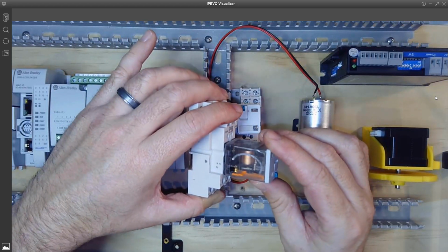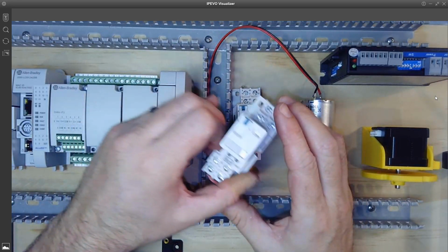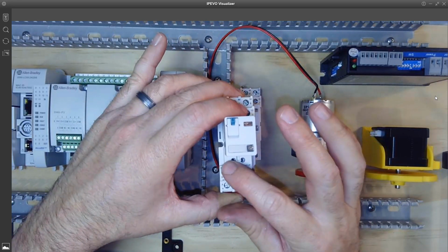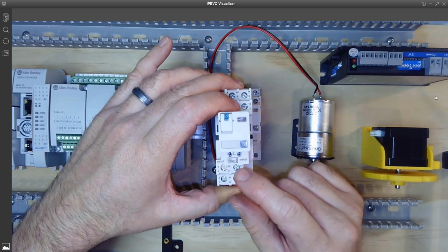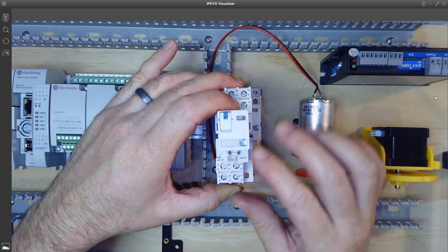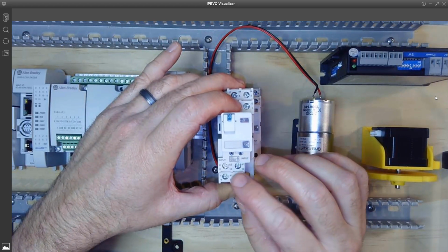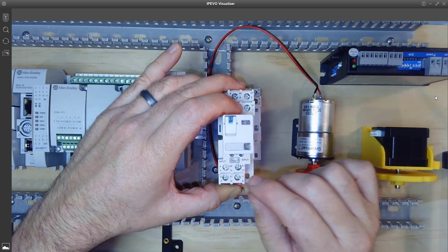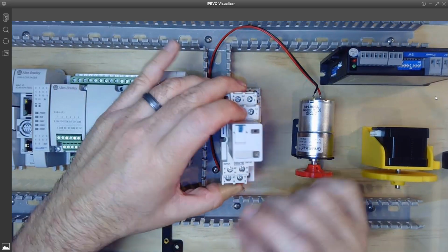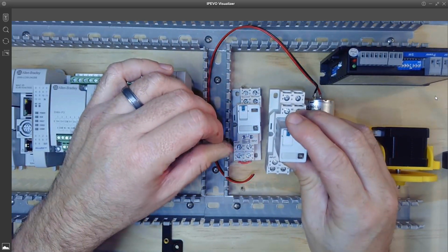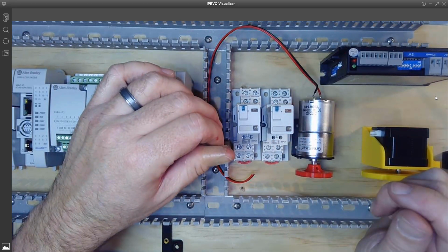And again, we talked about this briefly back in MEC233. The way we do that for a DC supply is we put a diode across the coil so that the diode blocks current flow in the normal direction when we are powering the relay, but then when we remove power from the relay, it allows current, that back EMF force, to flow in a circle and dissipate itself within the relay. So we'll go over that schematic a little bit, but I actually might just send you a reference to go look up that.